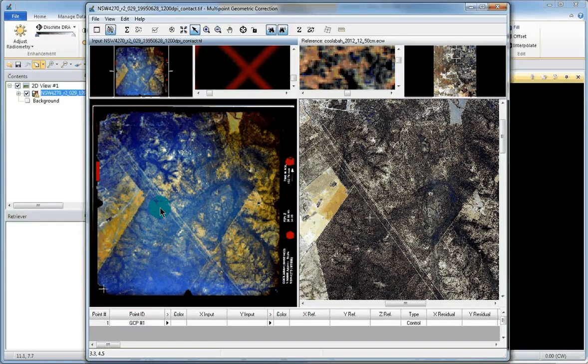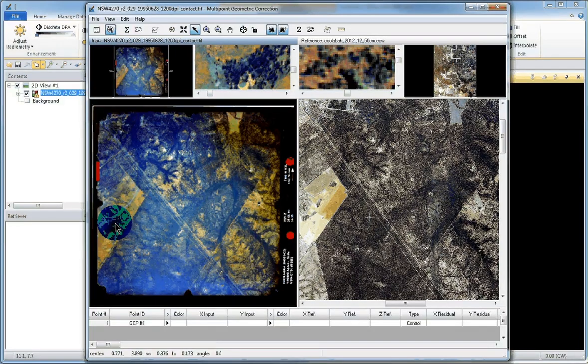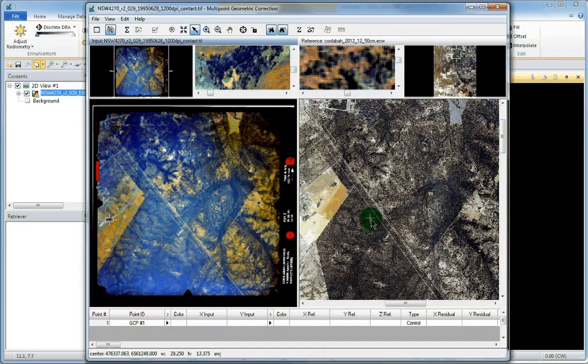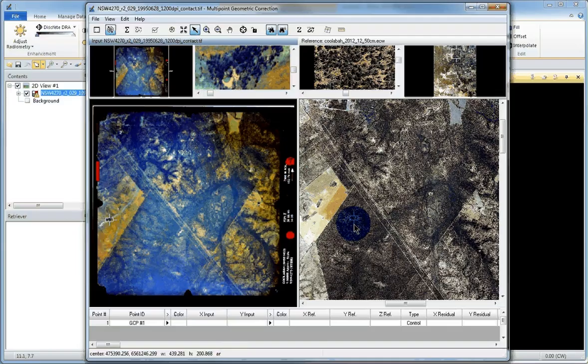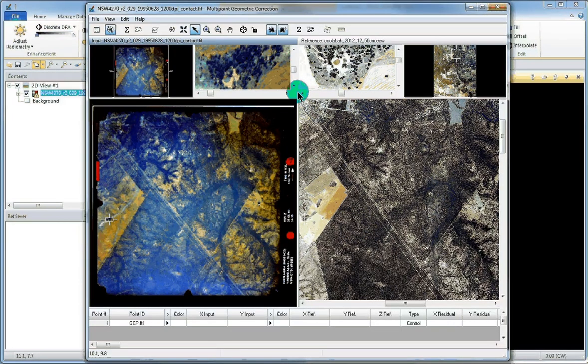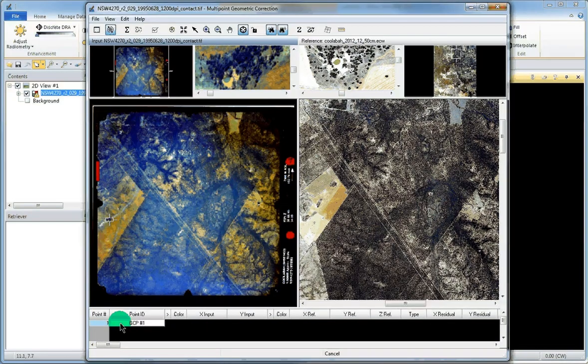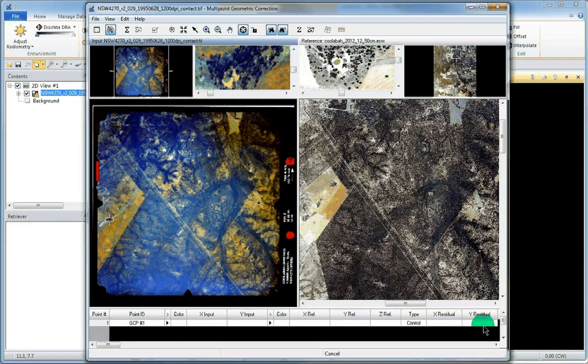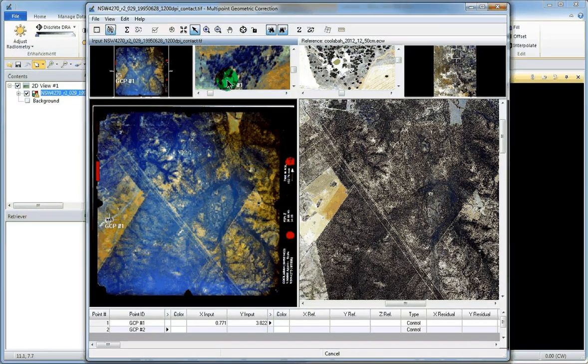Okay, so first things first, we'll enlarge our little selector box here, pick an area that we can recognise on both images. You'll see that it's showing in the top right hand box on this side, top left hand box on this side. We can select our crosshair tool. It's waiting for our first control point. The program is playing silly buggers again, and we can actually place our first control point, which I'll dump in the middle of the dam.